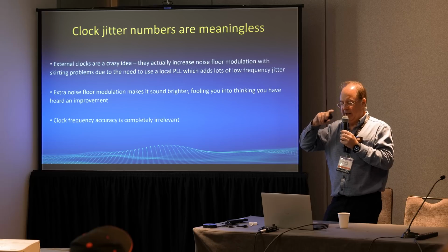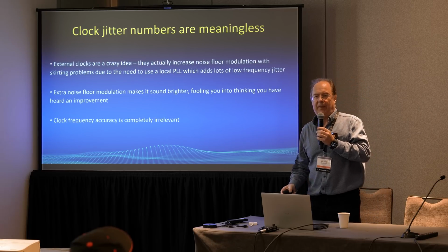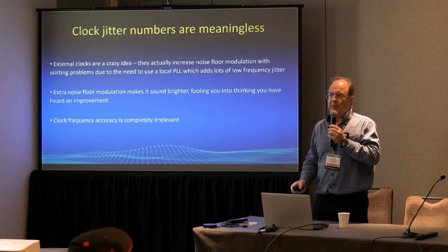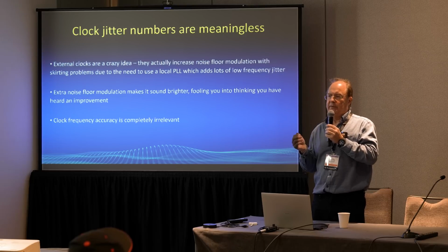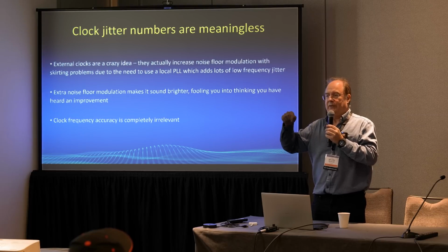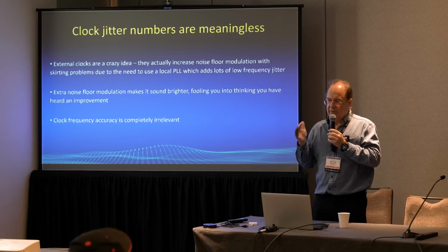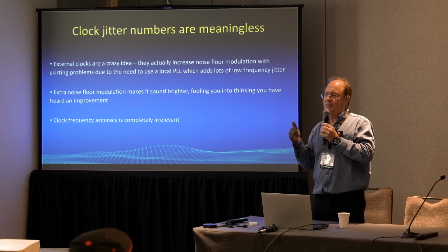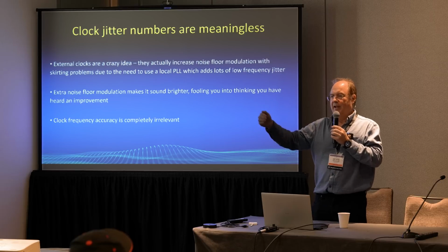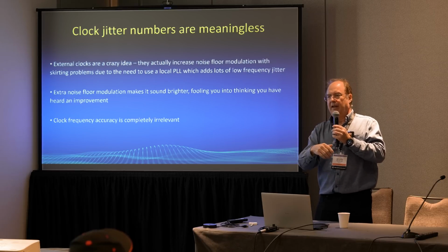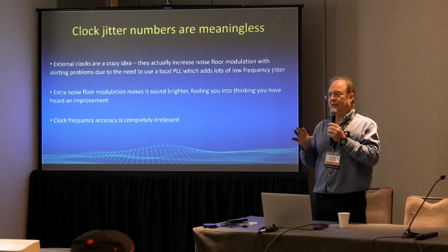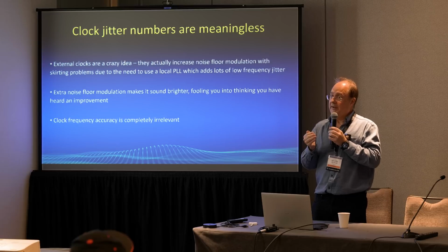Just one quick thing, external clocks are a crazy idea. The reason they use external clocks is it's something that happens within the pro business. Because in the pro business, you may have 64 A to D converters. They all need to be synced up on a common word clock, so you have a clock source that's separate and feeding through each individual one. The trouble with having a high-end DAC that's fed an external clock is that the clock is going through output buffers, it's then going through a cable, it's then going into an input buffer, it's then being converted into the DAC itself, and that is going to create huge amounts of jitter. So having external clocks is not a good idea.